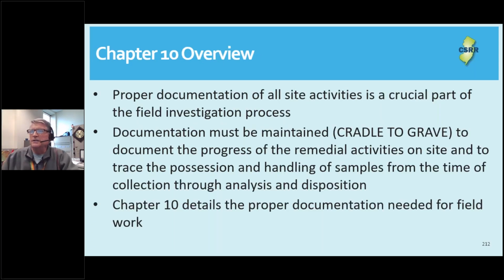Appropriate field documentation, field notes, field logs, photo documents. Photo logs are an important part of your field investigation process. It is critical as a basis for the technical conclusions drawn from the data that will influence and justify the remedial action selection. Documentation should be maintained from cradle to grave, because you're the individuals and professionals with boots on the ground at that particular site.